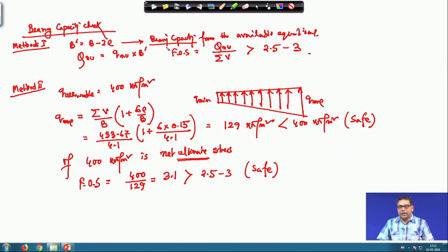In the next class I will discuss a few small things related to retaining walls. Generally, we prefer to use retaining walls with cohesionless soil, so that there should not be water inside the soil, or you can easily remove that water from your side, because this water will increase the stresses on the wall. So, what are the procedures that you should follow to minimize the water table effect during the retaining wall design?